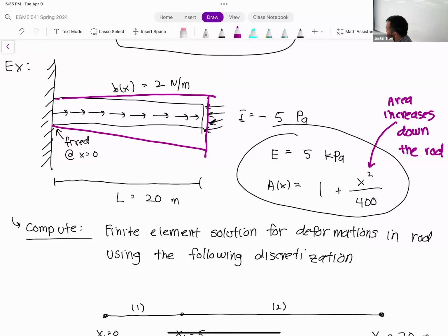able to solve with direct stiffness because, first of all, we have an area that's smoothly varying throughout the entire member. And we have a body force term, which is something that's new. Okay. So this is a situation where we can't just tackle this with our usual truss elements. We have to solve it directly from the differential equations because of how it's designed.